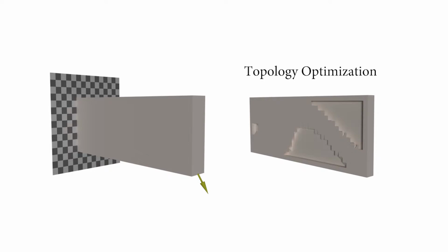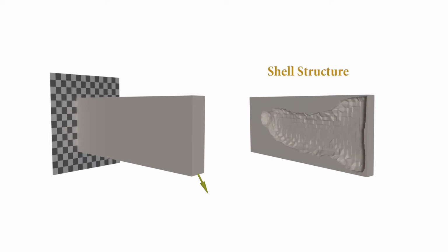In many design optimization methods, the resulting shape often contains complex internal structures. These structures create multiple isolated volumes inside the object, even for very simple loading configurations. They prevent easy removal of material encapsulated in them, and also disrupt the inner cavity that could be used for functional purposes. Shell structures provide a compelling alternative, where the object is interpreted as solid enclosed by two-manifold surfaces, creating a single connected cavity inside.